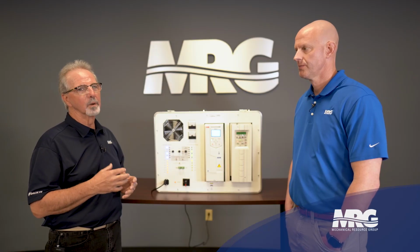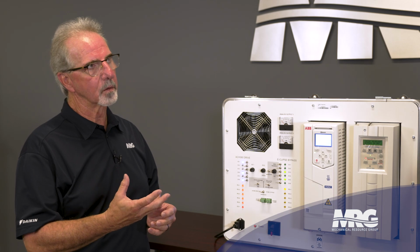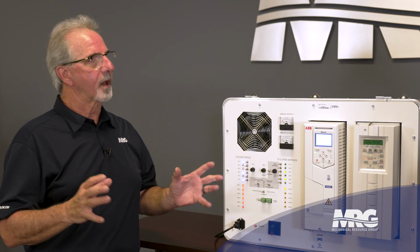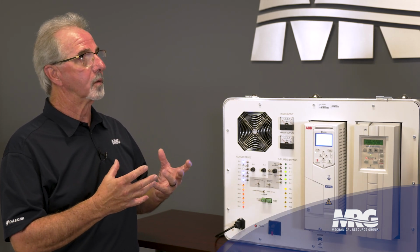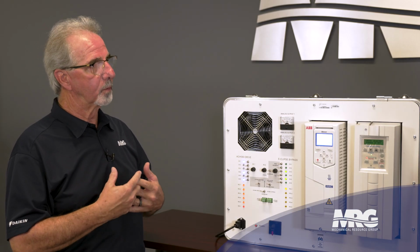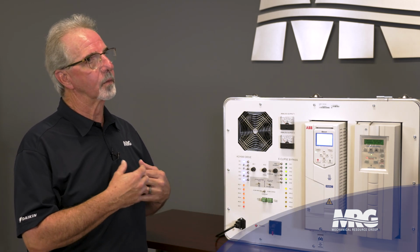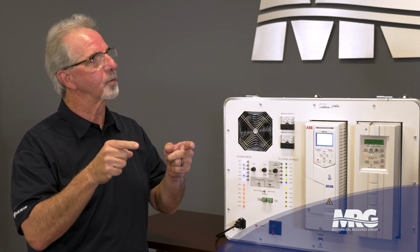And in 2022, we really started seeing them add elevator pressurization. Elevator pressurization is a little bit different. Same kind of stack effect that we have. We don't want smoke in there, because it used to be the old way the fire alarm used to do it: they shut the elevators down, and the only people that could go on the elevators would be the fire department. But now we have people with disabilities, and you can't get down stairwells. They'd have to be carried. And so there is an evacuation point in a specific elevator that they can go in and go up and down. We have to pressurize that elevator.